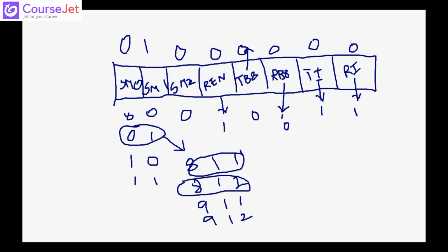This particular value is for transmission. When you say receiving, the mode is the same, the SM2 bit will be 0, but receive enable is 1 and the rest of the bits will be 0. So the SCON value will be 0x40 for transmission and 0x50 for reception. Okay, is this register clear?